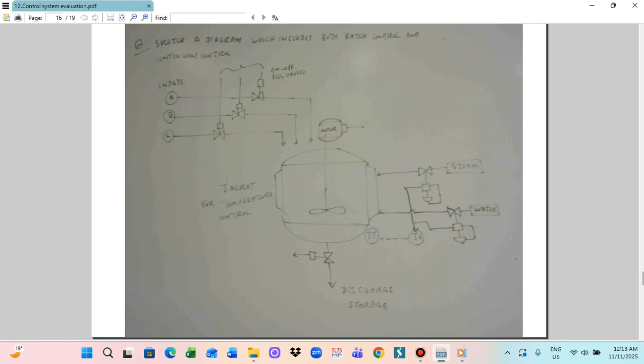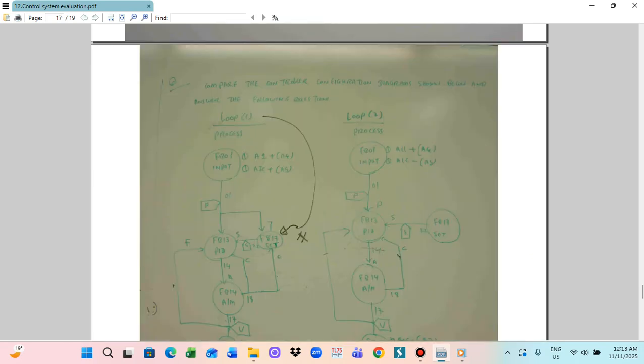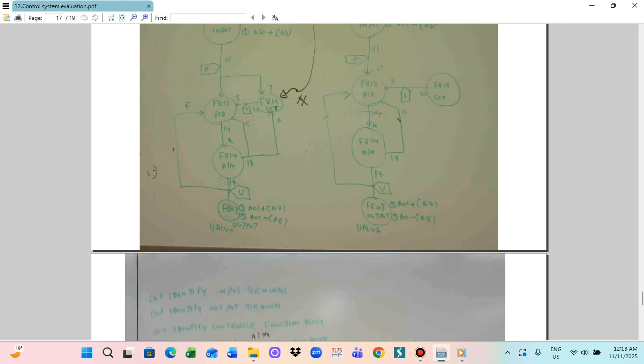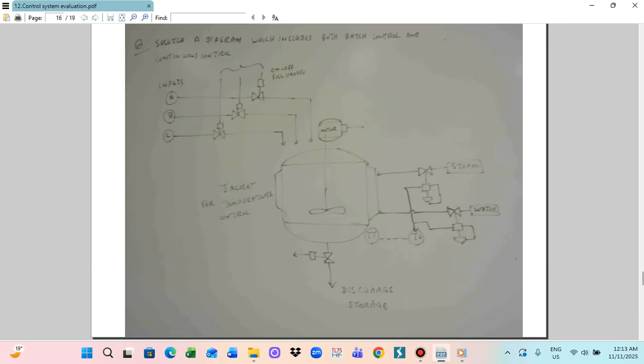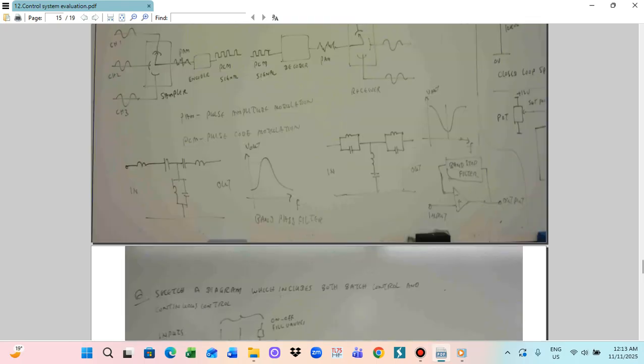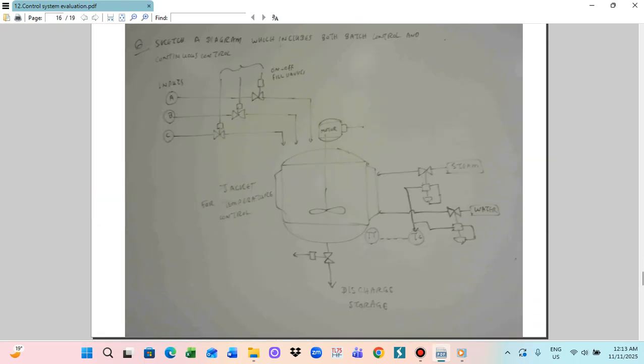So it is a discrete amount, rather than a continuous quantity. The required ingredients are fed into the process vessel in the required amount and in the right sequence. The vessel is then heated and pressurized in an appropriate sequence in order to produce the desired product. So in this case, we have to make a sequence control system.